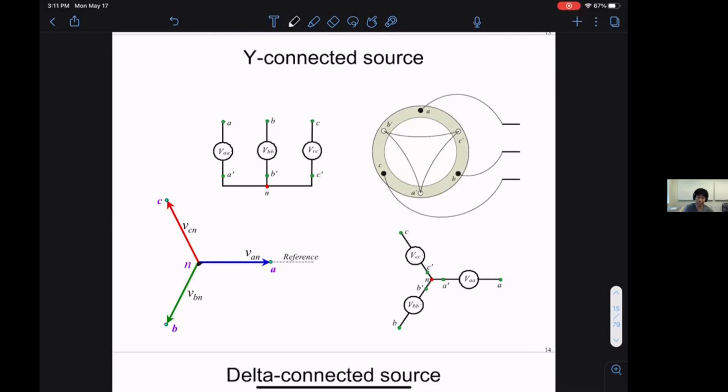So here in three phasors, because they add up to 0, we're going to think of the addition of them to be the origin or ground. So this is the way we're going to think about it. If it's exactly balanced, you don't need to connect ground to it because it wouldn't matter, right? The sum of it will be 0 anyways. From a phasor notation, as we have three phasors, the angles are offset by 120 degrees, add up to 0. So I'm going to treat this point, this N, to be neutral, the point that has 0 voltage.